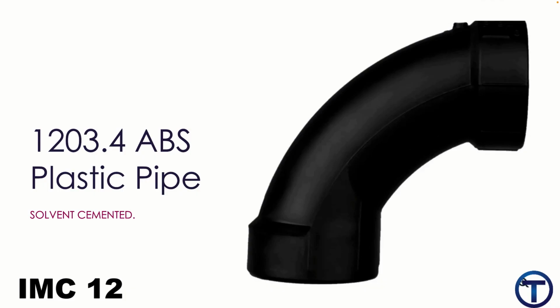Please notice that in a hydronic system, you're not going to be using the same ABS as you would for DWV. We're talking about solid wall, Schedule 40. This stuff's hard to find. In fact, I had a hard time even finding pictures of it, and that's why you get a DWV fitting on the screen right now. But don't use that on hydronic, please.